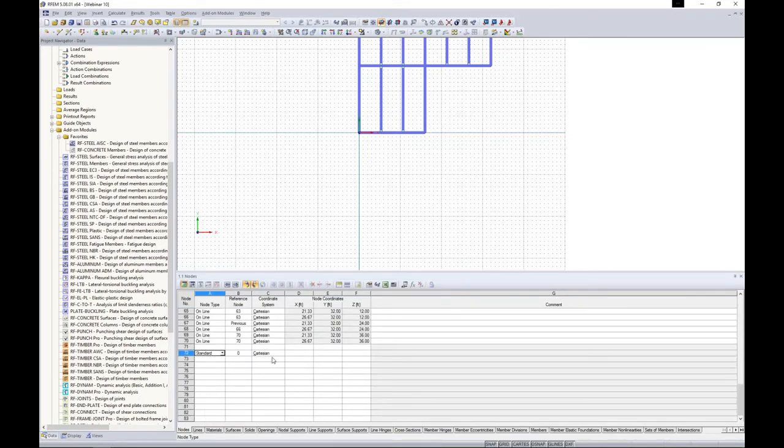I'm going to create my first node, and all I need to do is to specify the specific coordinates that I'd like to apply this node. So we'll start with -23 in the X, -25 in the Y, and Z will be 12. And then simply using my down arrow, I'll create my second node at 39, -3, 12, and lastly, my third option will be at 15, -45, and 12.